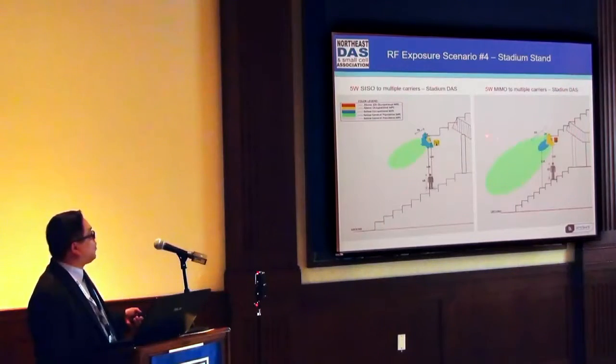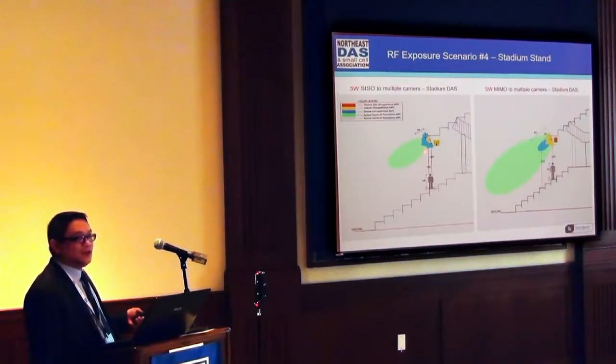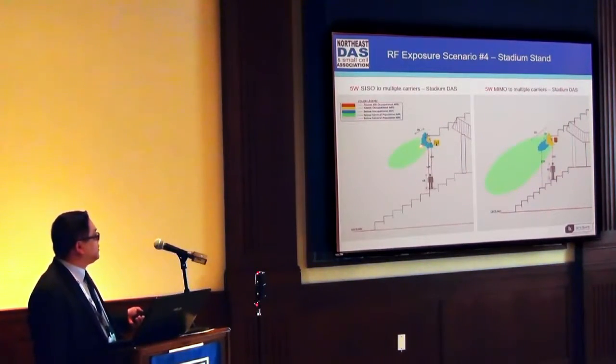Here is an example for a DAS environment. Again, you're starting to get closer to the people. Now let me ask you guys this. Have you ever seen a warning sign close to an antenna in a DAS? You haven't, most probably. And most probably that's never going to happen. But in reality, to be compliant, there is supposed to be a sign close to the antenna that would say, hey, I have an antenna over here, and there is a possibility that if you're changing a light close to these, within 2 feet or 3 feet of the antenna, you may want to turn off that antenna.